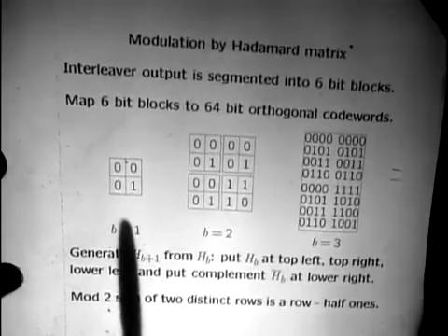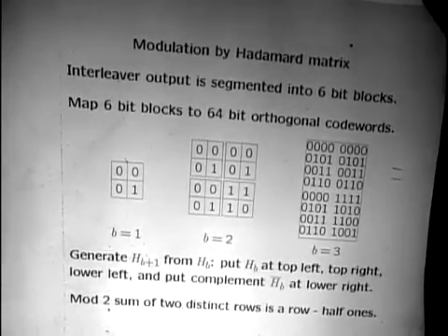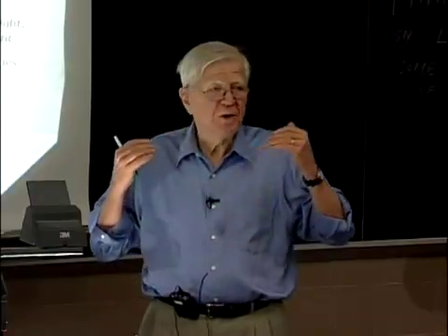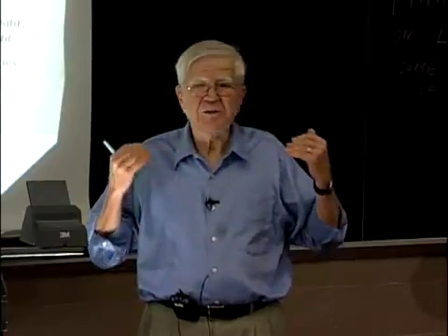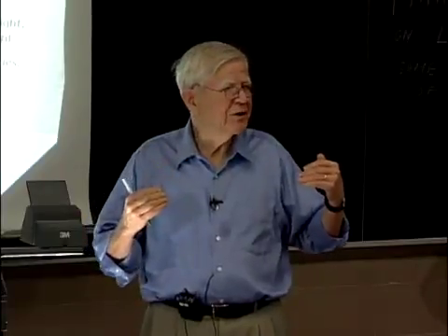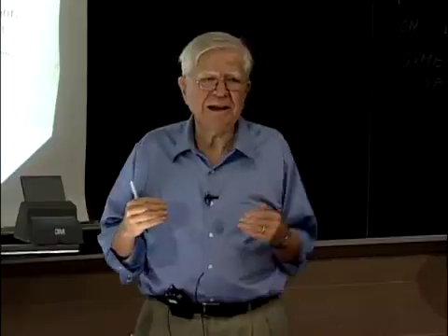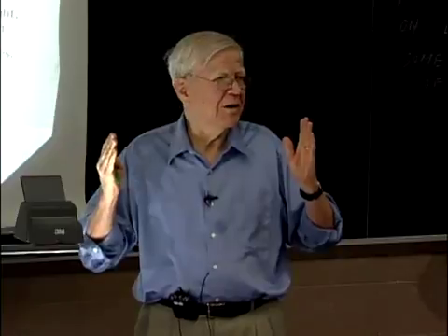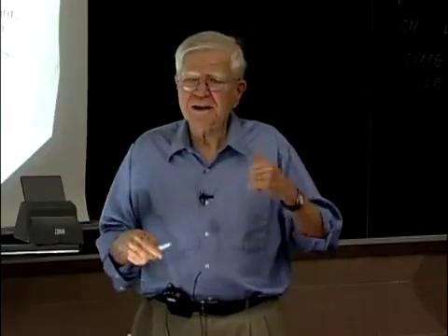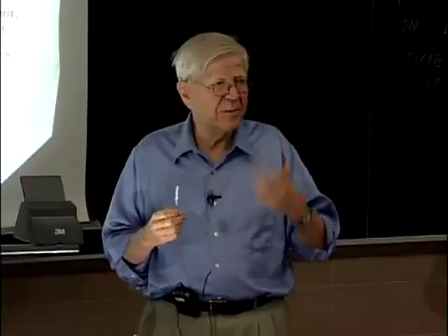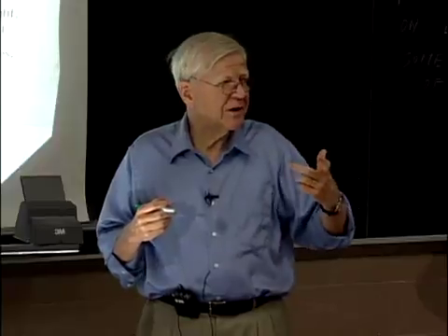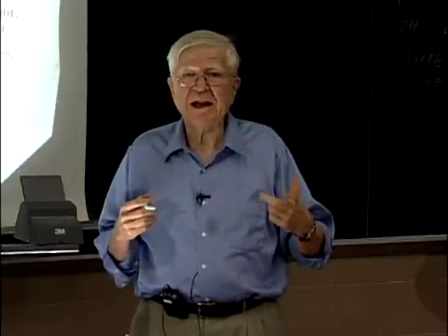which is why you think of it as being orthogonal. This is a confusion that runs through all of communication theory, and we might as well get rid of that confusion right now. When you talk about binary sequences and you say they're orthogonal, what you mean is if you turn that sequence into a 2PAM signal, those corresponding signals are orthogonal. In other words, an orthogonal set of binary sequences is a set of binary sequences where each of the sequences differ from each of the other sequences in half of the positions.